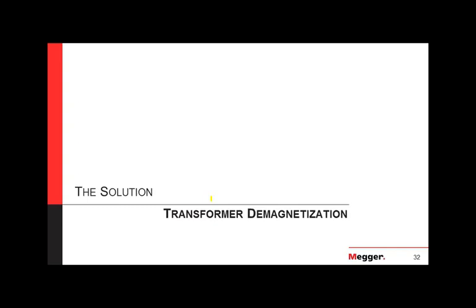So this L di/dt will be canceled. There's not going to be any additional change in the current going on the reactive component, and the only thing that you're measuring now is the current times resistance. So you apply DC current, right? And you measure the voltage drop through that coil, and that will be your winding resistance value. That's the reason why we use DC.